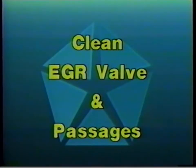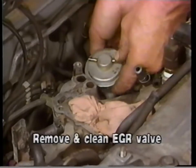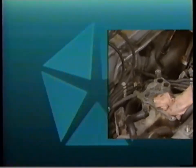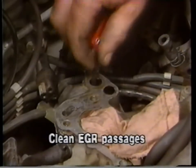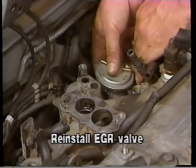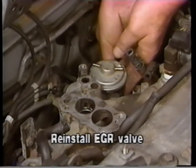The next part of this procedure involves cleaning the EGR valve and passages. To do this, first remove the EGR valve from the intake manifold and place a shop towel over the intake manifold carburetor openings. Next, remove any carbon deposits from the EGR valve and the intake manifold passages. After removing carbon from the valve and passages, use a new EGR gasket from the emission service parts package and reinstall the EGR valve.